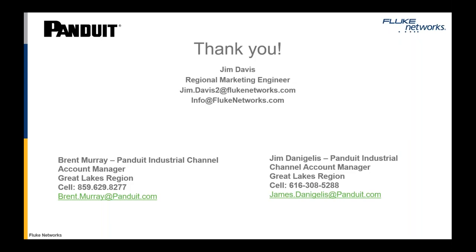Sure, looks like we have a few more that have come in here. You mentioned solid conductor Ethernet cabling. What are the advantages in using it? So Jane, I can take that. With the solid conductor cable, you're going to get better performance and a better length reach in running that cable. So for a permanent installation, it makes sense to use the solid core, so the cable's not stranded on the inside. It fits with a permanent part of the installation.